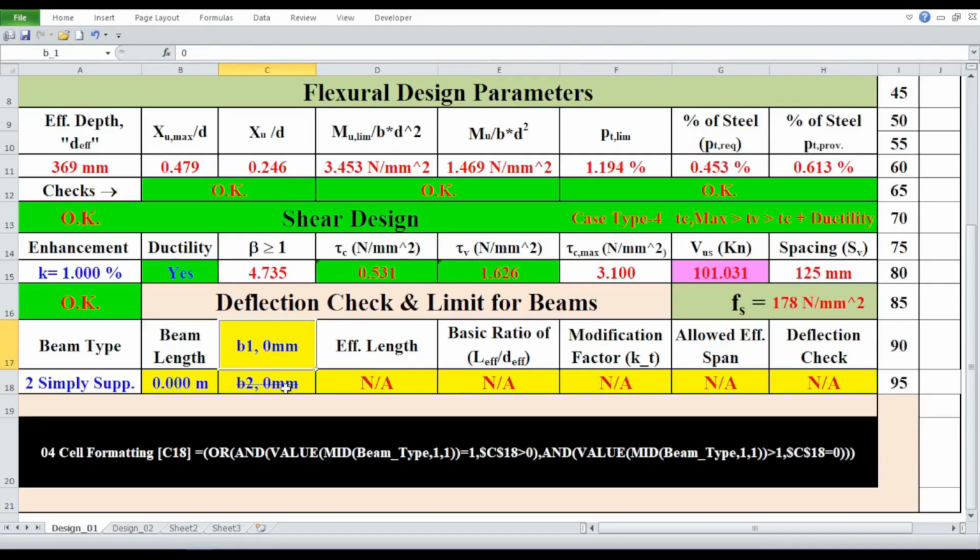Notice that cells B18 and C17 are filled with yellow. Also, observe cell C18, where the digit 0 has a strike through. This visual cue is due to conditional formatting. The conditional formatting rule for cells B18 and C17 is straightforward. If the cell value is less than or equal to 0, the cell will be highlighted in yellow. I trust this conditional formatting is easily understandable. Therefore, I will skip the detailed steps for its creation for cells B18 and C17.